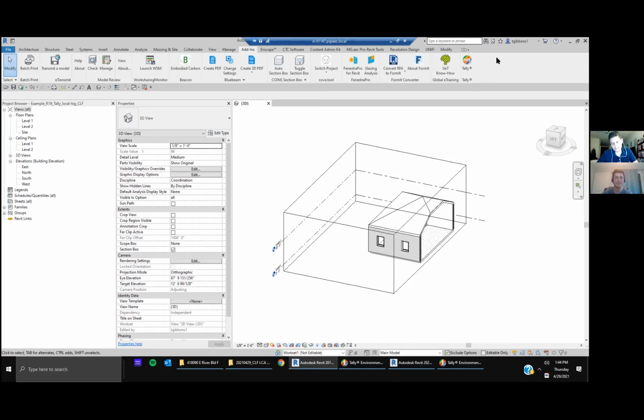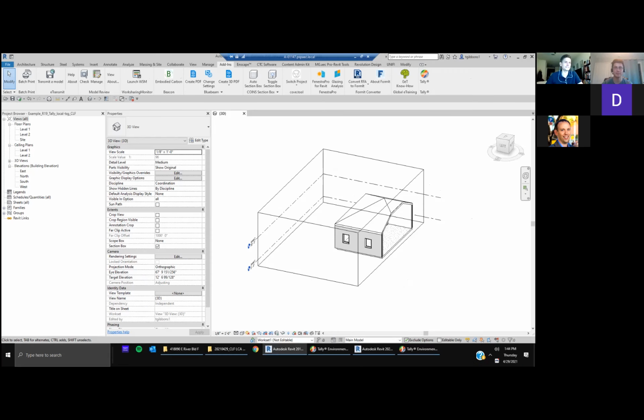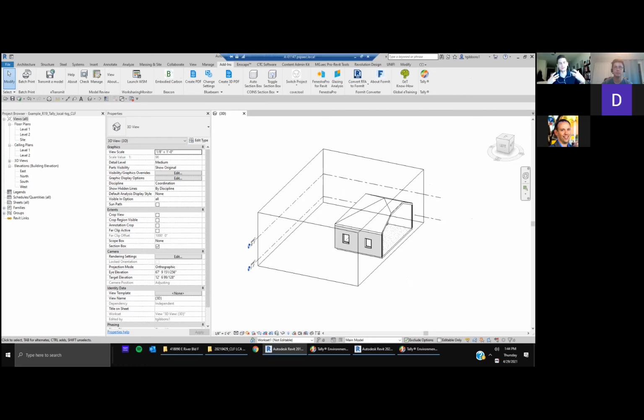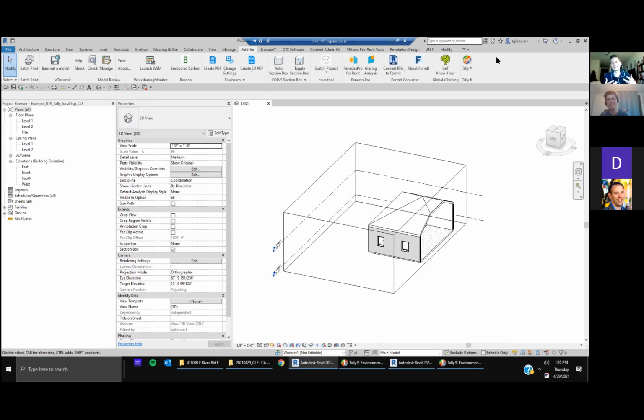I think about it like daylighting analysis. It kind of depends on where you are in the process. I like to detach if I'm going to do big whole building LCAs because I must have constant control of everything. So if I'm going to do a whole building LCA, I will pull the architectural model, and usually I will pull the structural model, and I will bind in the structural model, and I will then just hammer it. I'll just go through material by material, and we'll talk about this as well.